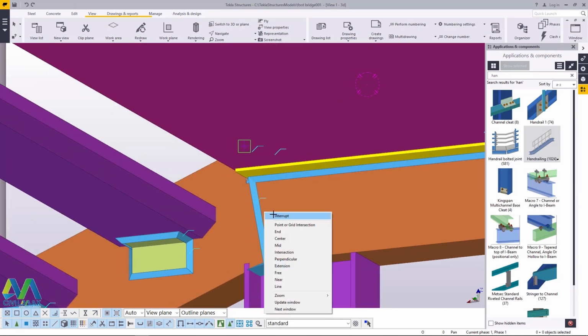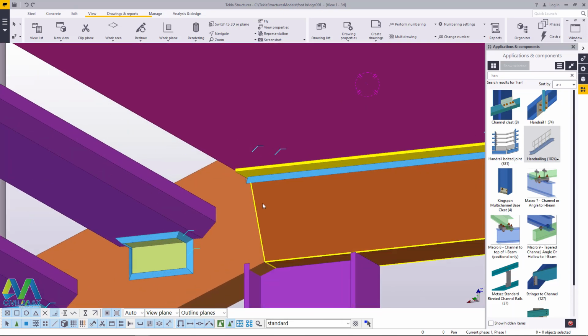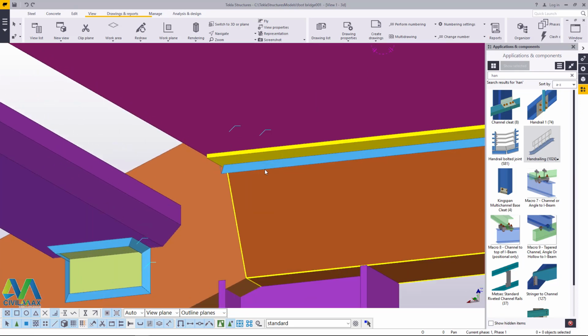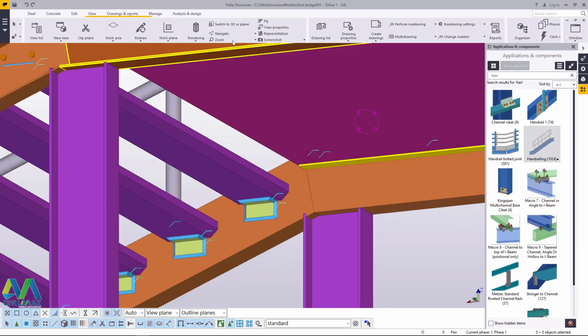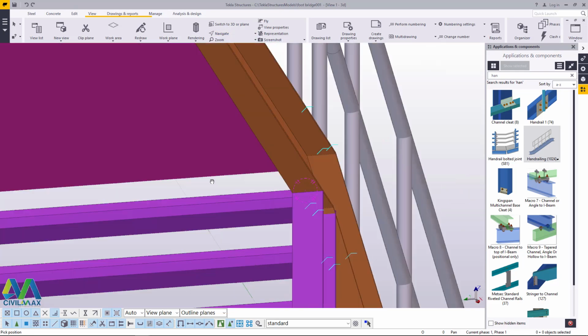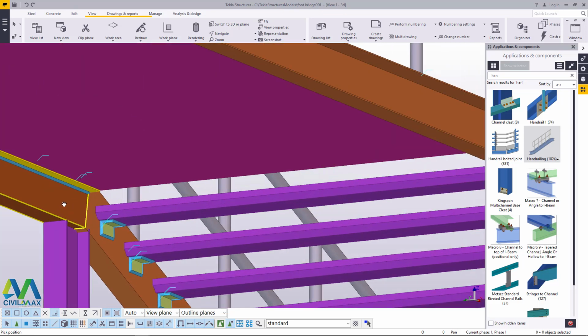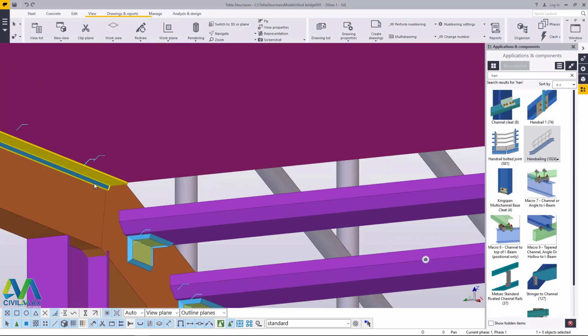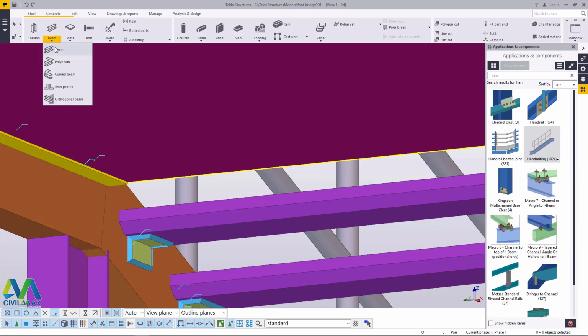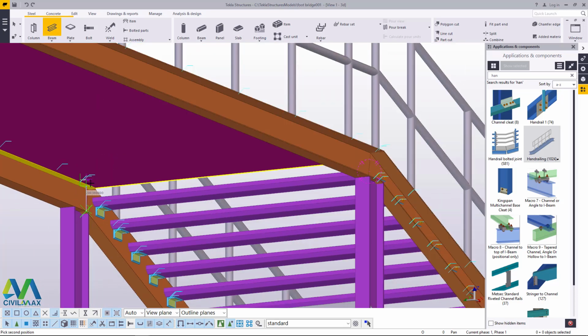Now let me get rid of this weld in this position because I want to see this place accurately, and let me get rid of that, and turn this and target and see the other end. Here also we have some weld, and we just need to remove this because we want to place our supporting frames to support the bottom end of this walkway. So I'll come to Steel here and pick the beam here, and I'll snap on that far end.